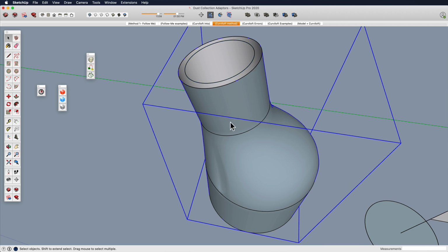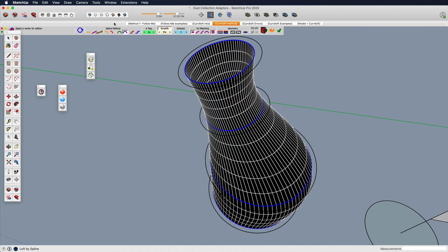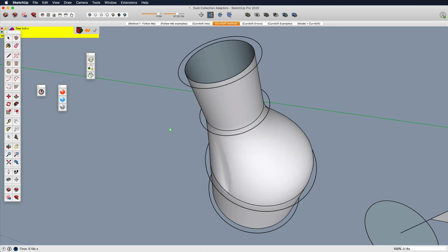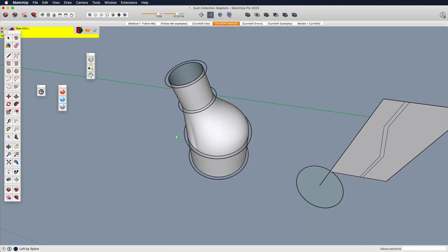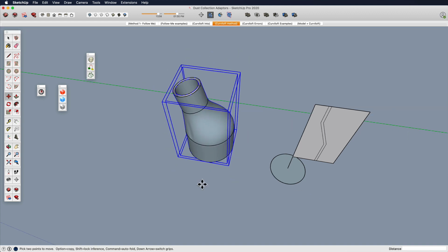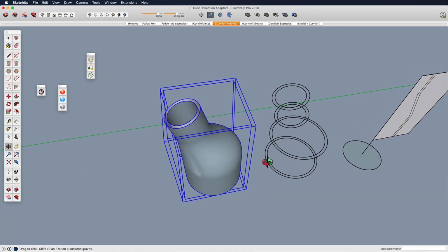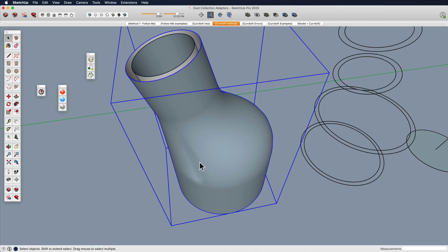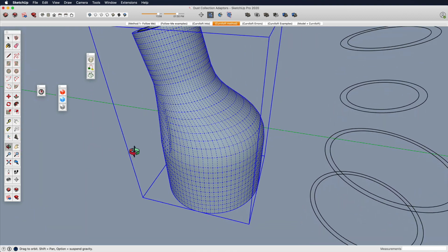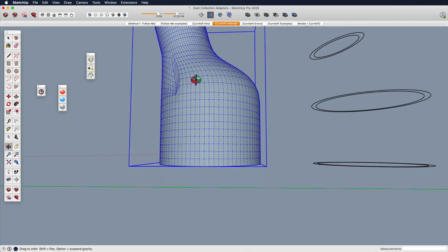Do the interior one. I'm going to take this and hide it for a moment. So this interior one, hit this, change the spline method so that you get that, and accept that. Okay, if I unhide, it'll create these as new groups and leave your original geometry if you want to keep messing with it. Again, that was a little weird. I might go in to figure out what, but that would still work. So I might do some tweaking to see what's going on, but right now this will work.